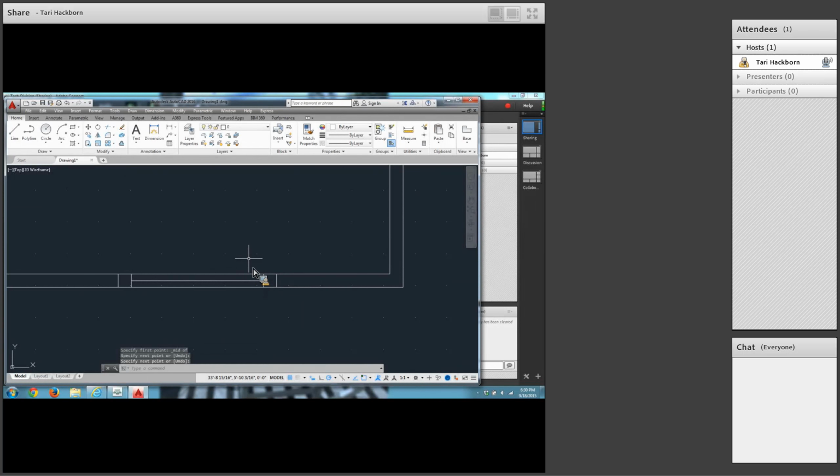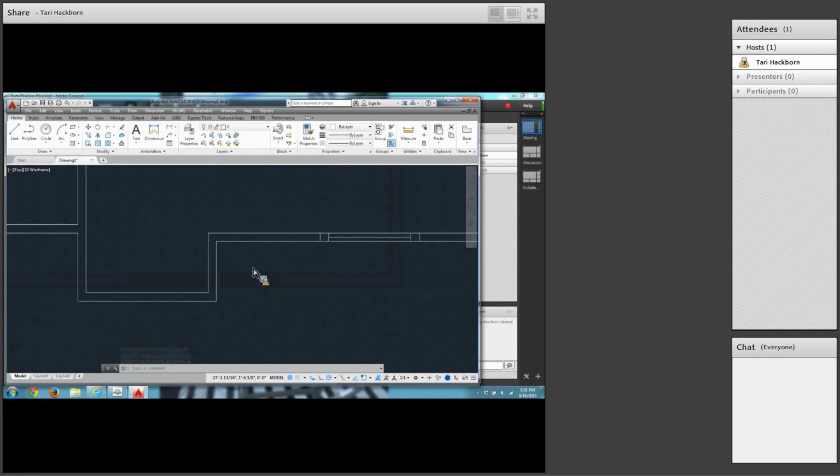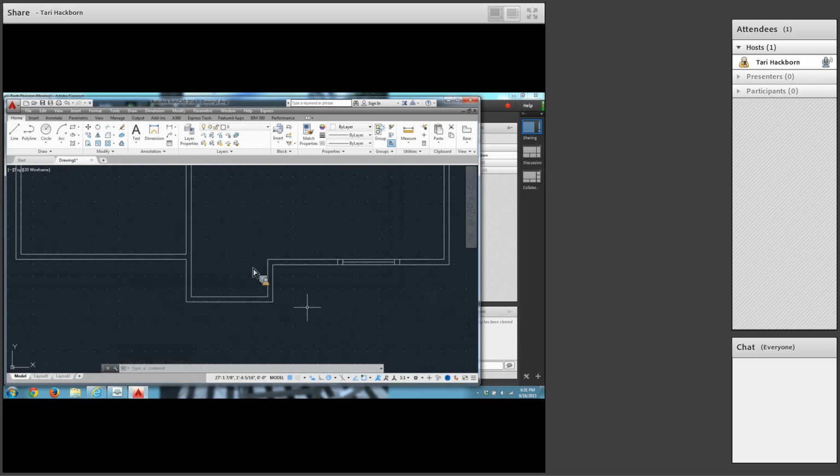Now, anything that you can figure out to save you drawing time is great. Maybe I could copy this window to the other side where there's also a 5-foot window. In that case, the 6 foot 6 offsets from the outside walls might be helpful. It gives me a base point. So you could select copy.